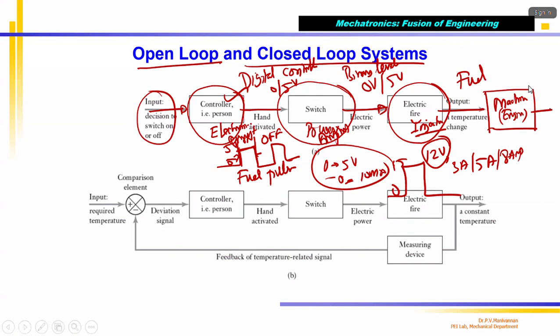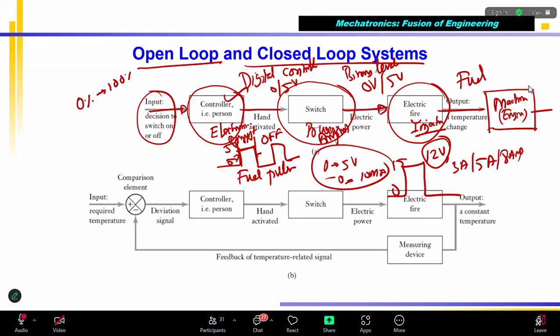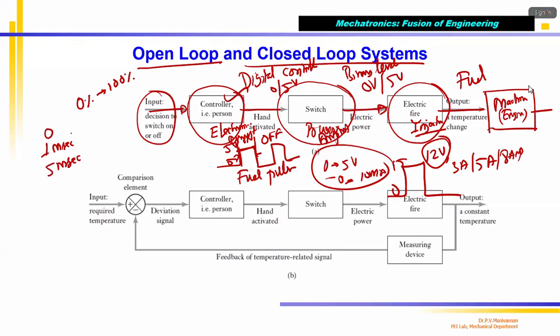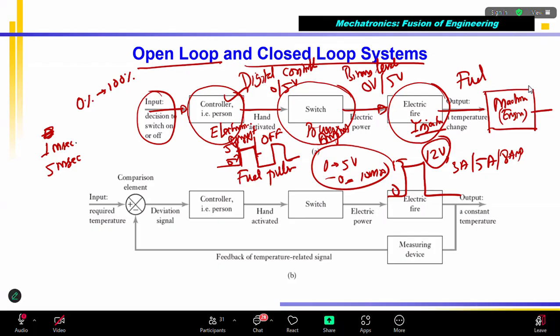The engine is running. We know that in open loop control, if I press the throttle, from 0% to 10%, what should happen is the fuel injection pulse will vary from 1 millisecond to, for example, 5 milliseconds. Correct. Sorry, 0 is not possible because the engine has to run at idle RPM. Generally, at least you have to have idle RPM, otherwise you cannot drive your vehicle. Even to run the engine, the driver needs pulses. So my pulse duration will be 1 millisecond.